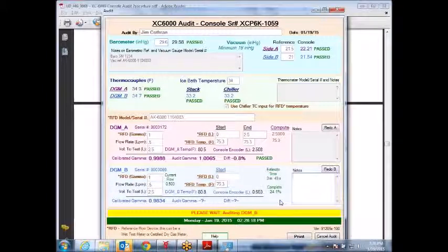We had a PowerPoint we were looking at. Anyway, it has this under Apex dry gas meter audit. Under the gas flow meter calibration, they had a frequency at 3 settings prior to initial use, and at least quarterly at 1 setting thereafter. Correct.